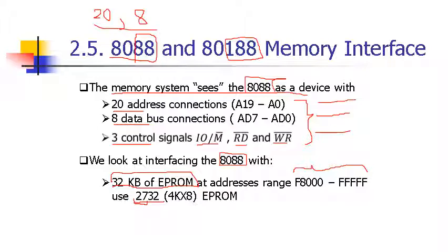The total number of bits inside this memory chip is 32K bits, organized as 4K memory locations, each of 8 bits. So the chip is composed of only 4K bytes. We need to interface 32K bytes of memory using chips each of 4K bytes. So we're going to use 8 of such chips. So this is the first problem.